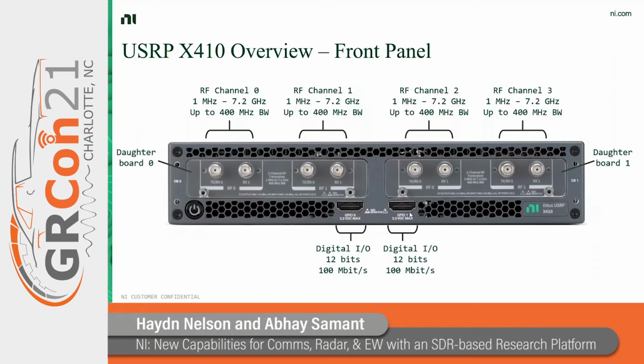So here's the front of the radio. It's pretty cool. Come by and take a look. You'll note one striking omission here that, if I was in the audience, I would poll the audience and see if you could identify it. You'll notice there are no local oscillator imports and exports on this radio, which is important for people wanting to do phase-aligned multi-channel synchronization. We decided not to include that feature on this particular radio, ultimately to keep the cost at a reasonable level for the applications for which we think people are going to use this. So I just wanted to highlight that.